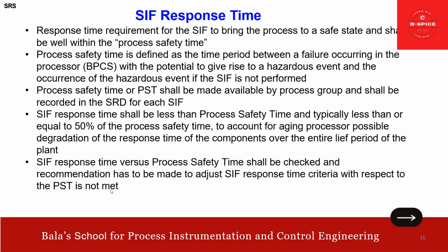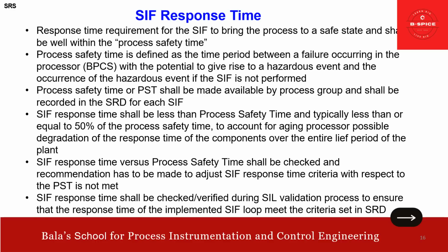SIF response time versus process safety time shall be checked, and a recommendation has to be made to adjust the SIF response time if the criteria with respect to the PST is not met. Okay, I hope you also got this. The SIF response time, very important. Okay, friends, right.